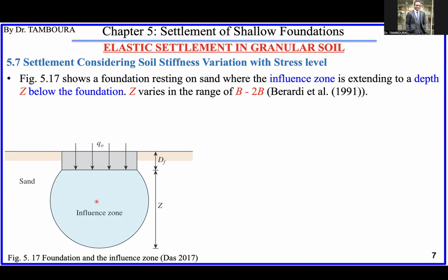This is just your sand. So this is the influence zone of this load, and the maximum depth it will reach is this Z. Df is just the embedment of the footing. This Z is very important because it allows us to know down to which zone the load is going, and until which zone we can consider for the calculation of the settlement.